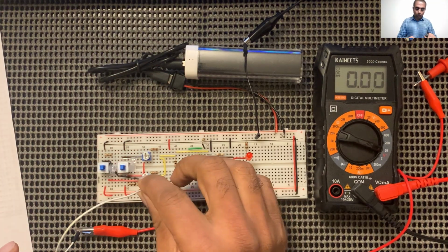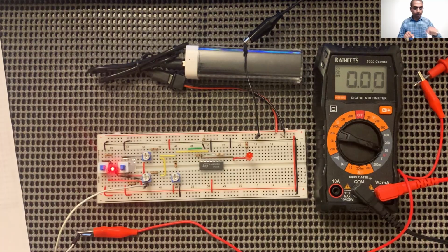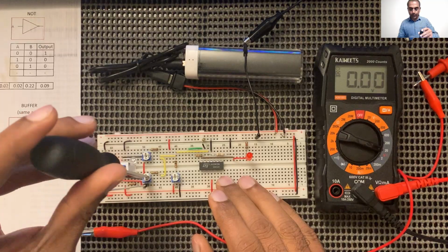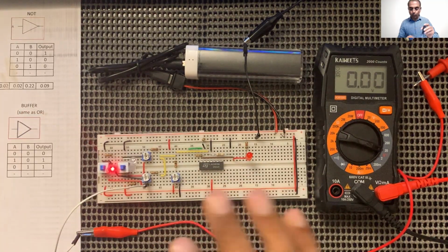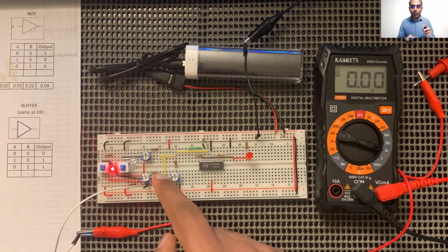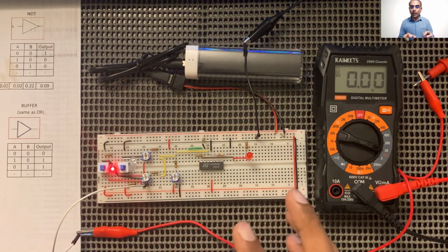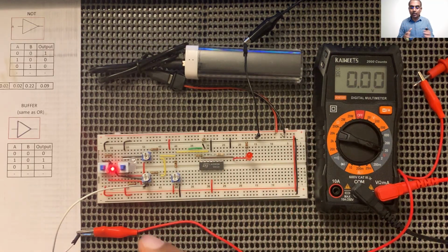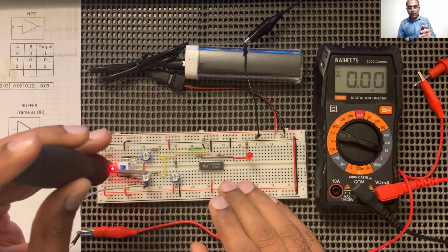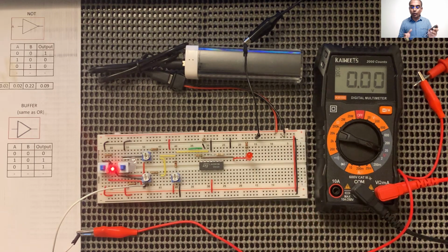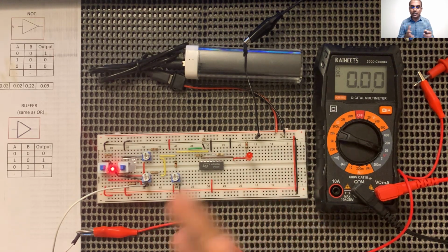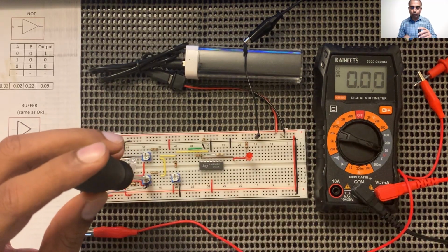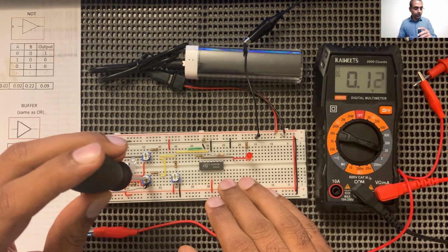Now let me go on to potentiometer A and then set that to value 0.28. Right now this potentiometer is at 0 volt. See, this is one of the problems with a breadboard. Any vibration or little bit of shaking will destabilize the circuit and may produce an unexpected output. But it is easy to use a breadboard. You can pop in and pop out any of these components at your will, and you don't have to necessarily know how to solder and all the related issues with soldering.